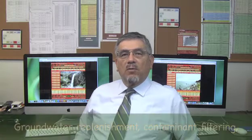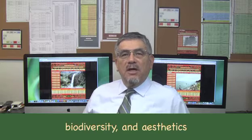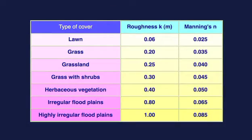In summary, while a rigid boundary channel focuses on conveyance effectiveness, a vegetated channel takes into account a host of environmental concerns, such as groundwater replenishment, contaminant filtering, biodiversity, and aesthetics. Vegetated channels are increasingly being used in hydraulic engineering. This table shows values of absolute roughness K and Manning's n for various types of vegetated channels.